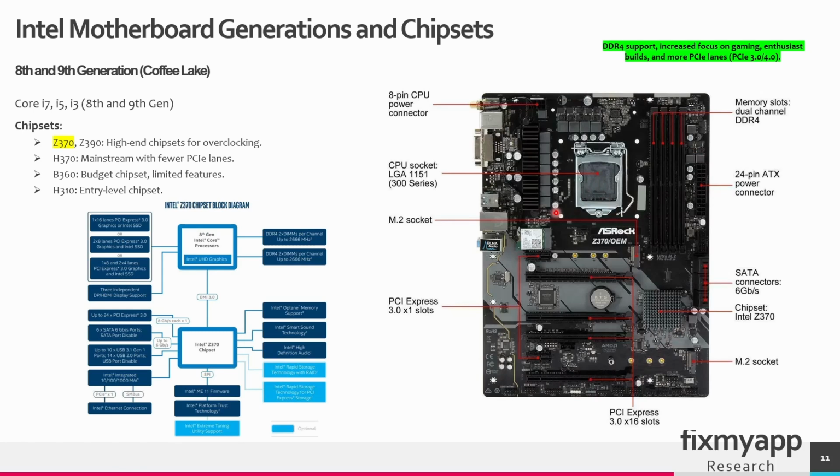So we have the CPU part, we have the voltage regulators, RAM memory slots, the chipset underneath a heatsink, M.2 slots, PCIe slots. So the first one will probably be the high-speed part, and it will go to the CPU part. This will probably be the audio part, because we have an audio chip and some capacitors. This is the RTC part, and this is probably the Super I/O. So the physical layout is still the same. Maybe some small components are located in a different area, but on the whole, it's still the same motherboard physically.